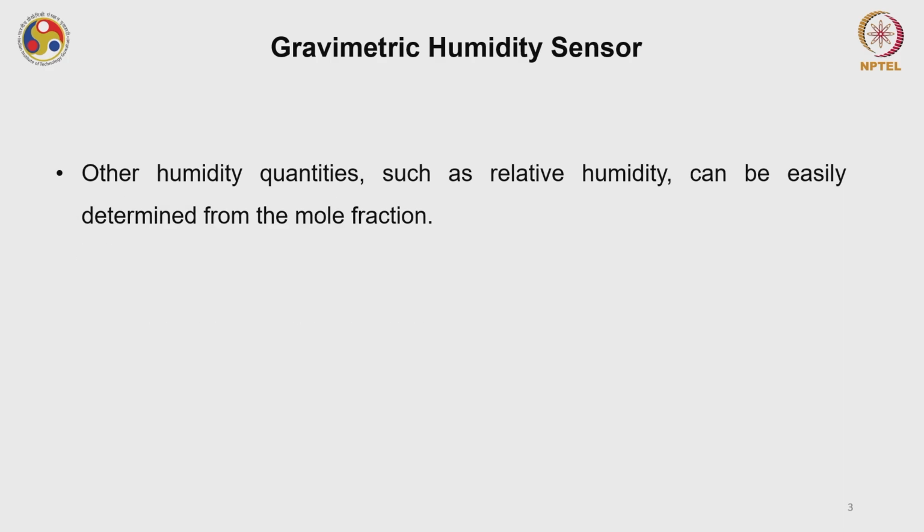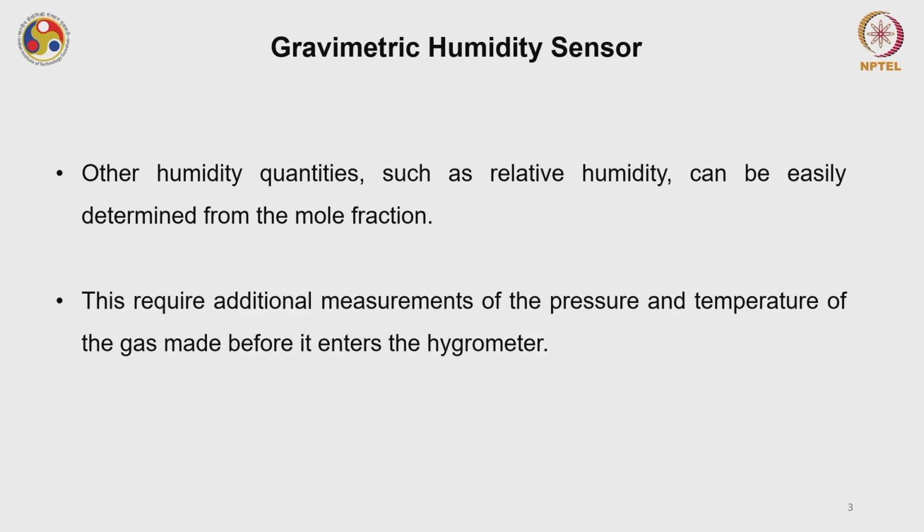The mass that this balance measures is used to calculate the mole fraction in the gas. We discussed yesterday different humidity quantities, particularly absolute humidity, relative humidity and specific humidity, and we discussed that relative humidity is of utmost importance for us, particularly because of its importance in industrial applications. When you have this mole fraction of humidity through this micro balance, you can use it to calculate the relative humidity.